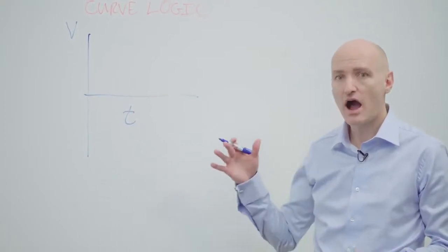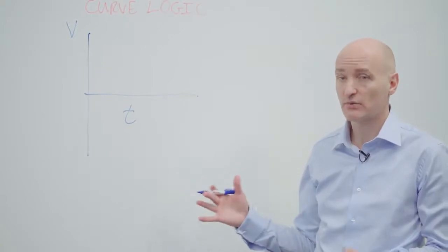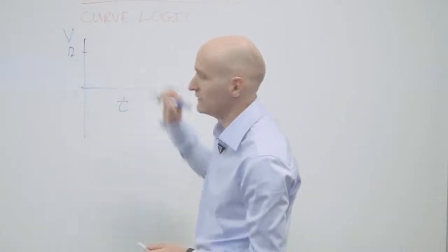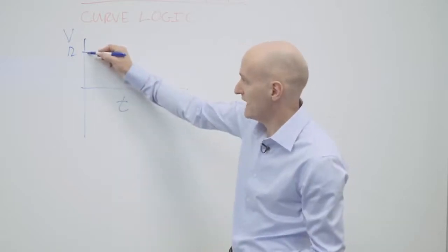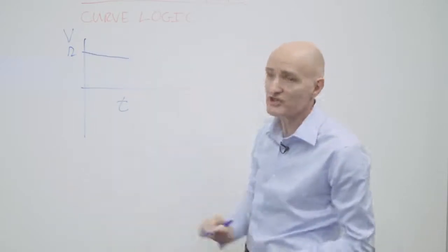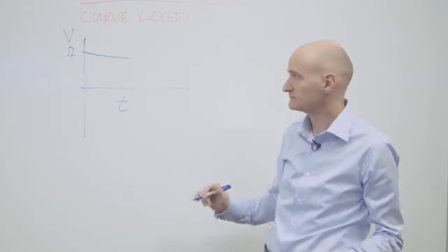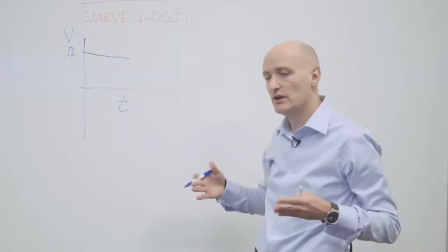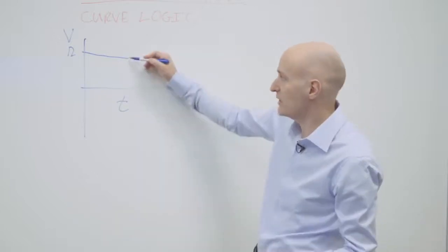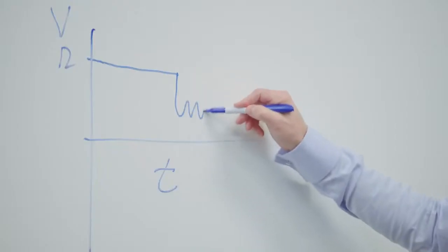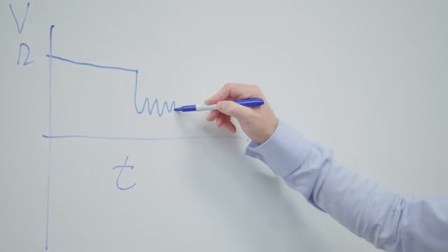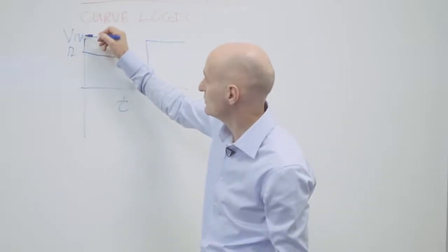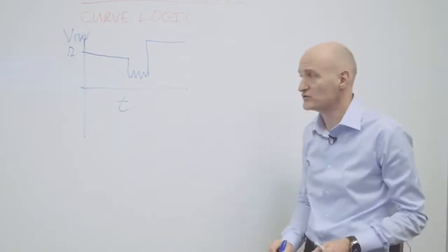So how can our curve logic and our intelligence help with that? Very clever. What we do, we know battery voltages in vehicles are 12 volts. So we know that if that thing is degrading over time, you're discharging the battery. So we know that you've left the lights on. When you come to start the vehicle, an interesting thing happens. You're essentially putting a short across the vehicle, and the starter motor is then engaging, and then you get a ripple effect as the starter motor engages, and then it goes up to 13.4 volts, which is the voltage where your alternator charges the battery.